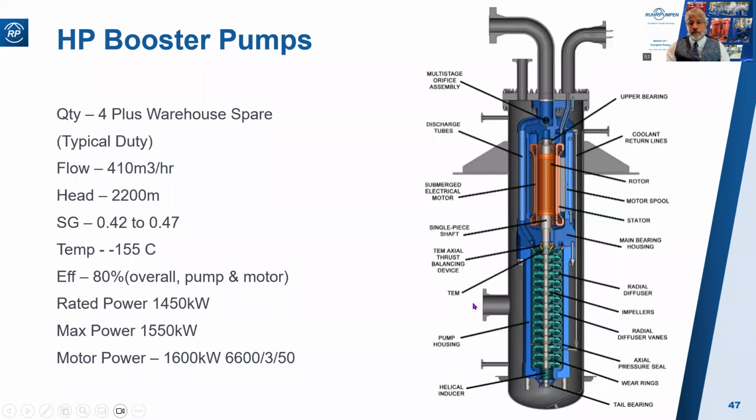So again, the flow comes here, into the pump, multi-stages, could be 15 stages, discharges out the top into 4 tubes around the motor housing, which join up together at the top and discharge here. Here is the electrical connection.